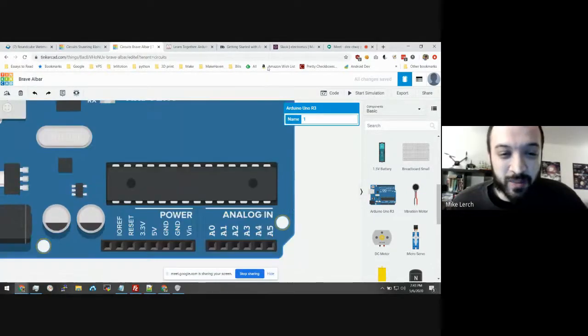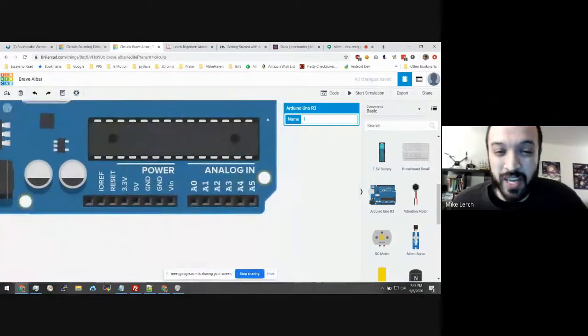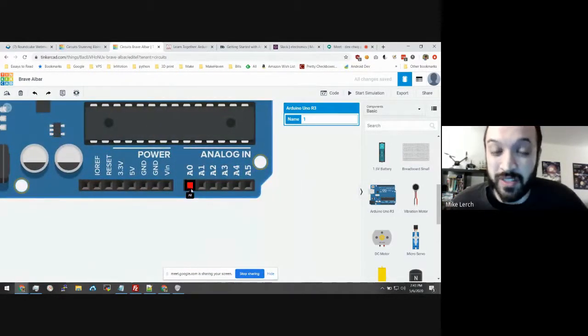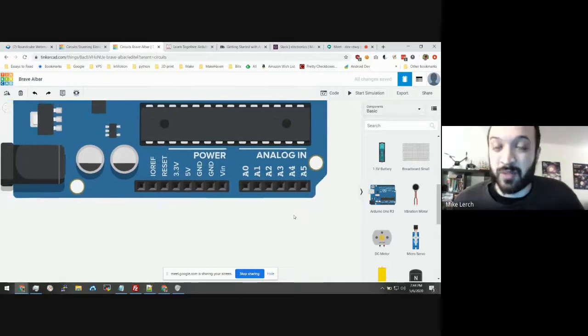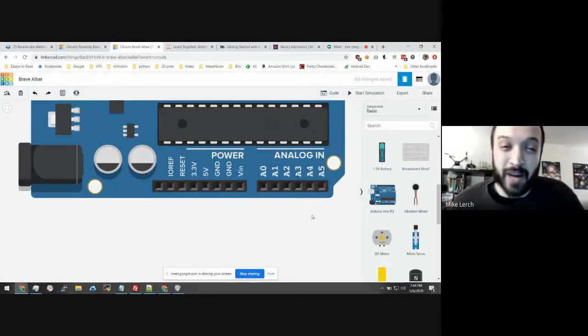And then on the other side of the board here, opposed to digital pins, we have analog pins, which is 0 volts to 5 volts. So on the other side of the board, you had digital pins, which are binary, 1 and 0. On the bottom side of the board, you could have voltage analog pins down here. And again, these are both inputs and outputs. So you could have any combination of these controlling a separate device like servos or motors or LEDs or what have you, or acting as input devices like some sort of button or dial or knob.